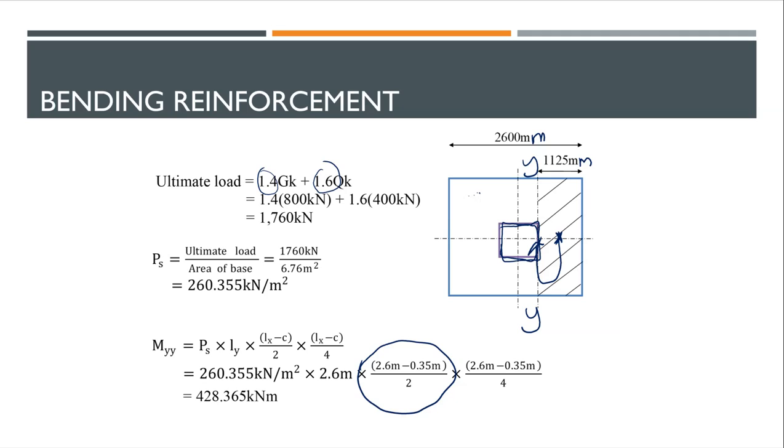Why do we say that is the critical area? Basically, because you have this line, YY, which is the most critical line, because you have force coming from above. At this point, right next to the column, it will transfer to the foundation, and your foundation is also right at that line. So usually the crack will be here. Okay, the connection, because yes, it is a connection so it is actually critical at that part.